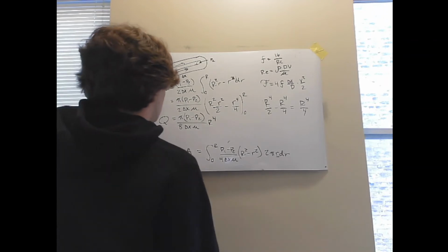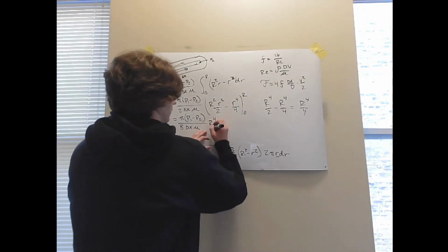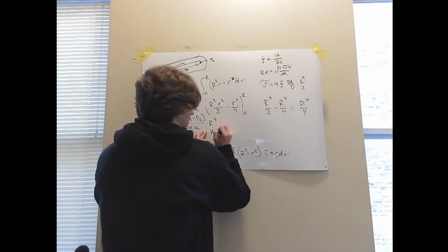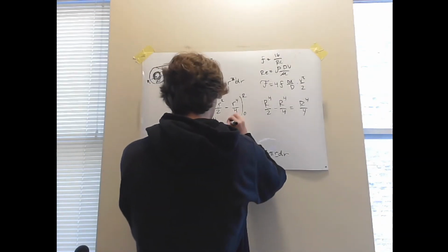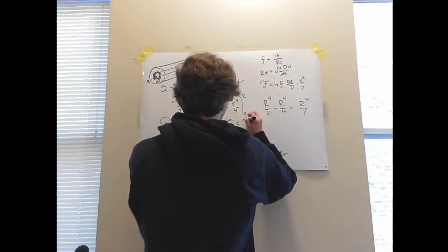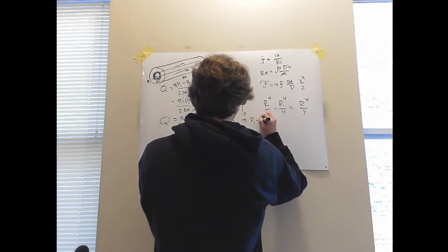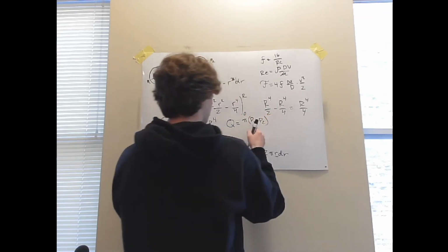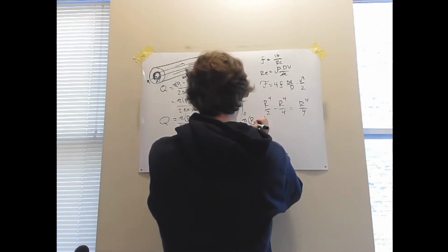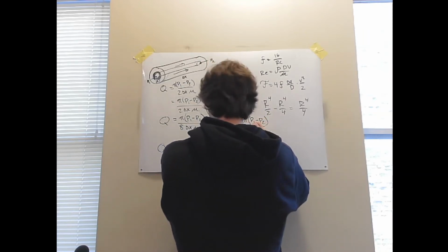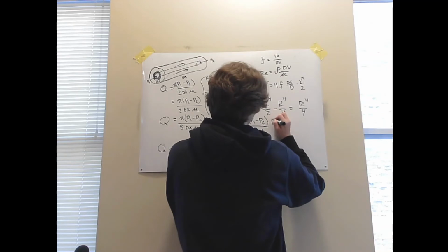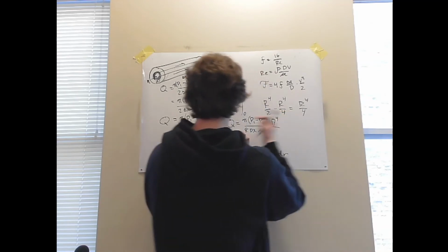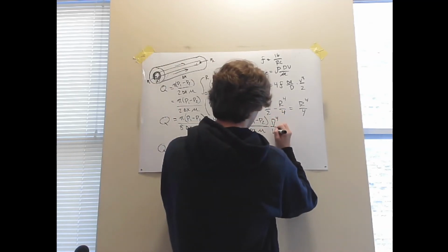So to put this in terms of the diameter, we just have to keep in mind that r equals d over 2. So our new equation for Q in terms of diameter, really not much changes. We still have pi times the first pressure minus our second pressure over 8 delta x times mu, but instead of r to the 4th, we now have d to the 4th over 2 to the 4th, which is 16.